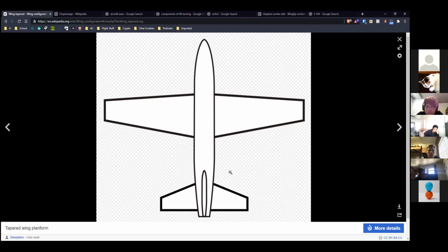because if you stick your hand out the car window and point it forward into the flow, then if the air catches your hand or starts to deflect it, it will start to deflect it more and more, like the force increases. Whereas if you trail your hand out the back of the window, then the air kind of supports your hand. If you deflect it, it pushes it back towards neutral.